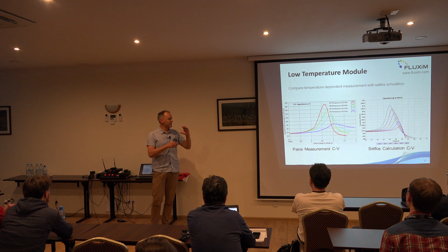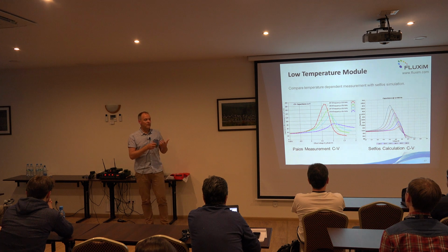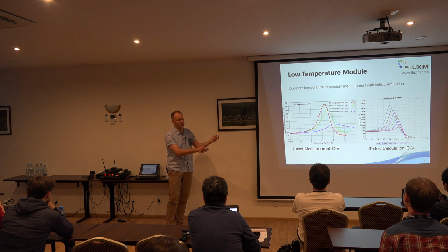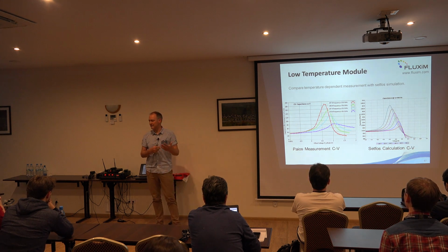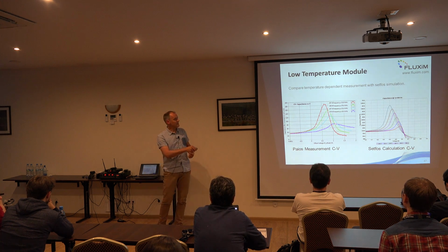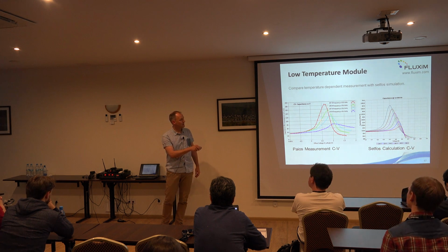So if this energetic barrier for injection from the cathode, from the electrode to the semiconductor, at lower temperature, this barrier becomes effectively higher, and therefore the peak position moves to higher voltage. So that's also nicely as expected. For lower temperature, charge injection starts at a higher voltage. That's the measurement on the left.